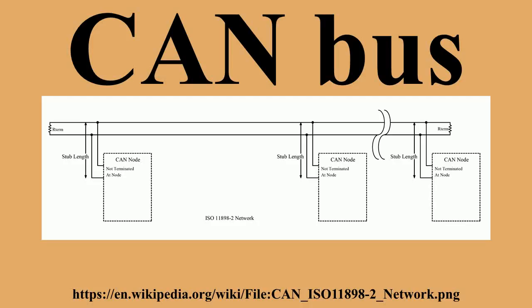The exact voltages for a logical 0 or 1 depend on the physical layer used, but the basic principle of CAN requires that each node listens to the data on the CAN network, including the data that the transmitting node is transmitting. If a logical 1 is transmitted by all transmitting nodes at the same time, then a logical 1 is seen by all of the nodes, including both the transmitting node and receiving node.